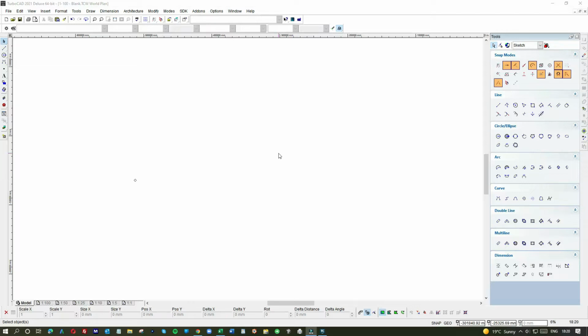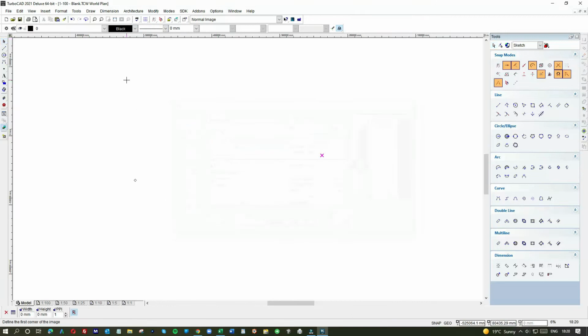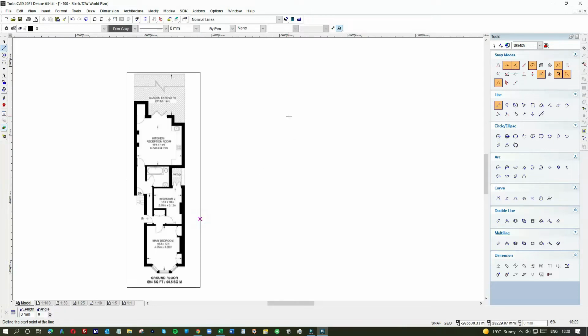Right, so let's get down to work. Earlier in the day I took some PDFs and took a few photos of drawings within the PDFs. We don't actually bring the PDF document into the model space. What we actually do is insert photos and we scale from the photos. So if I go to Insert, Picture from File, and select a photo I created earlier, all I do now is click once and then drag, and when I'm satisfied, I click again and lo and behold we have a photograph.